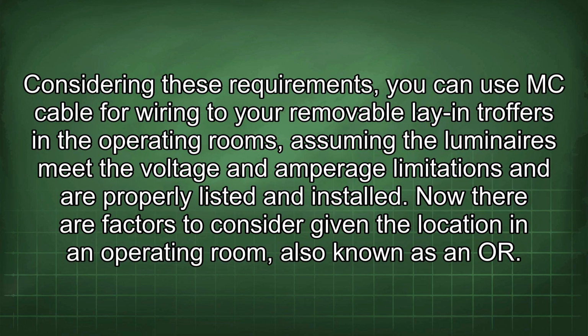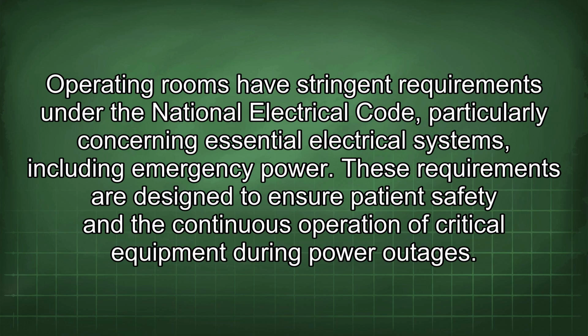Considering these requirements, you can use MC cable for wiring to your removable lay-in troffers in the operating rooms, assuming the luminaires meet the voltage and amperage limitations and are properly listed and installed. Now there are factors to consider given the location in an operating room, also known as an OR. Operating rooms have stringent requirements under the National Electrical Code, particularly concerning essential electrical systems, including emergency power. These requirements are designed to ensure patient safety and the continuous operation of critical equipment during power outages.